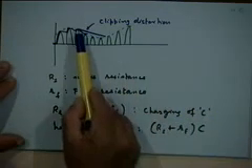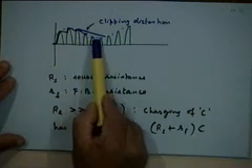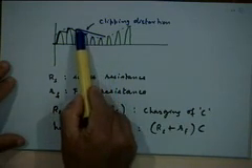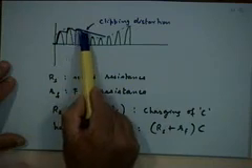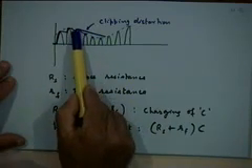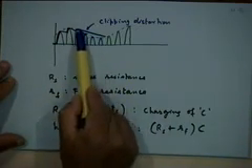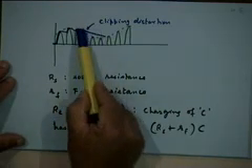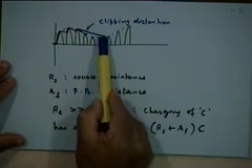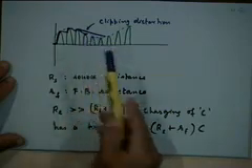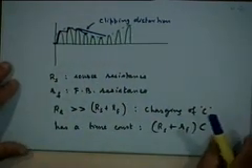You just want to make sure that while the rate of discharge is slow, it is not so slow that you fail to capture the fast fluctuations in the envelope itself, right? So you are comparing this rate of variation with the rate of variation of the message waveform, the envelope. Is that clear? Carrier frequency does not enter into the picture at this stage. Okay. So that is what the envelope detector is all about.